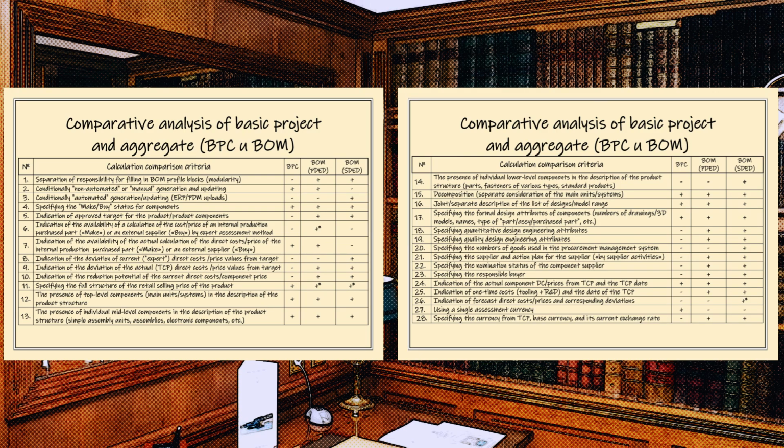Looking ahead, I will say that within the framework of the design-to-cost methodology based on value analysis, the BOM is firstly modular and secondly combined or universal, i.e. its form is uniform, from the pre-design milestone to the start of mass production. Depending on the milestone, individual columns or entire models or BOM blocks are allowed to be filled out. The advantage of the combined option is that all the milestone data is presented within a single file. The disadvantage of this approach is the cumbersomeness of the file, both horizontally, in the number of columns, and vertically, in the number of rows.